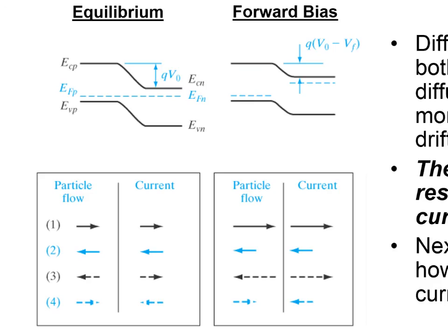It is electrons. How do we know it's electrons? Because of the direction. Exactly. The current is in the opposite direction as the particle flow, so we know that it's electrons. That's good, we're halfway there. Some people are saying it's drift. Just by looking at these 2 arrows, we know that it's electrons. But how do we know that we're talking about drift current as opposed to diffusion?